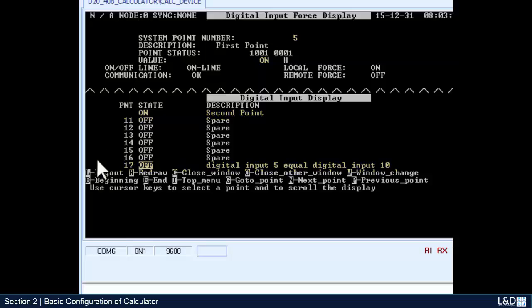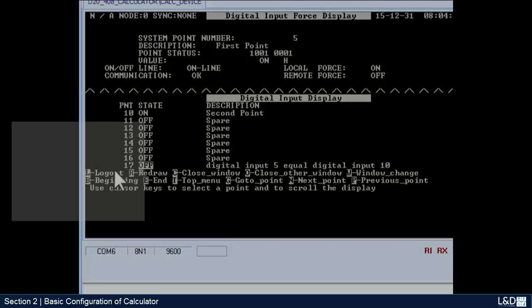So depends on what logic you want to show to your operator, but this is a very simplified way of taking a very simple situation that you have at the site, where you need to compare 2 digital inputs before you send it to your operator, and send him an alarm whenever those 2 states are not equal.